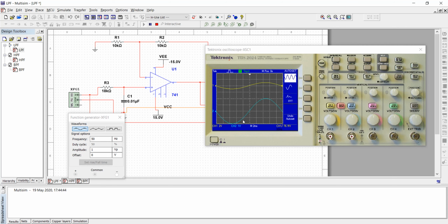As the name of the filter suggests, low pass filter, all low frequency signals will be allowed, so it is an amplified version. Here channel 2 is 1 volt. If we go to the measure part and select channel 2 type, frequency, here we can see the mean type. Peak to peak voltage is 4 volts. So it is an amplified version that we get for channel 2.